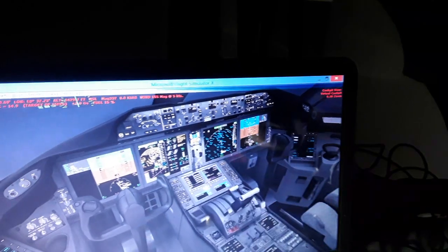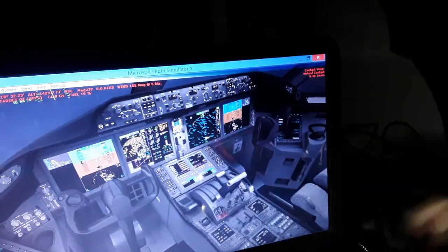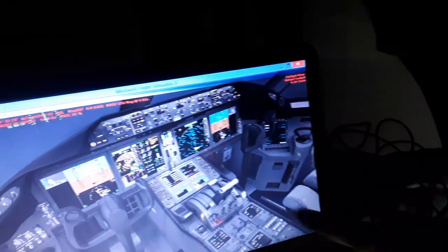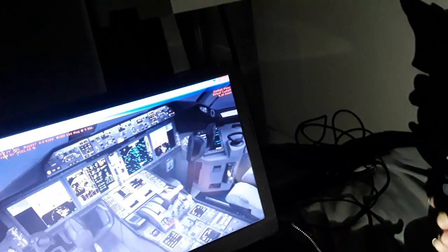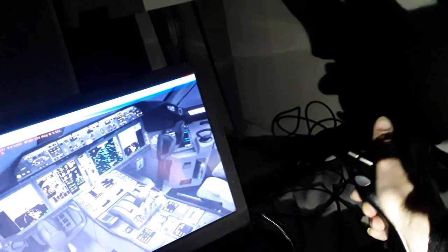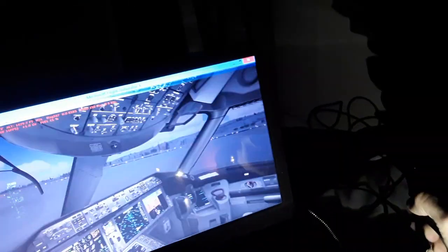The parking brake, the normal brakes, the thrust reversers from the engines, the flaps and slats, the speed brakes, horizontal tail, aileron, spoilers, rudder, all need hydraulic pressure from the engines, or the APU as a backup. So we have the APU also to start the engines.